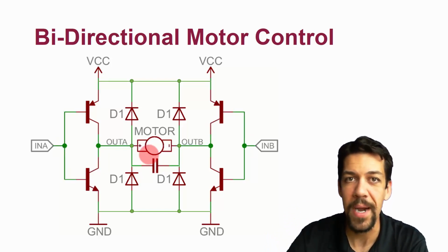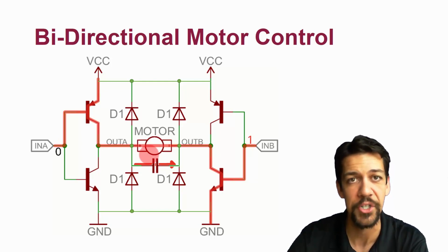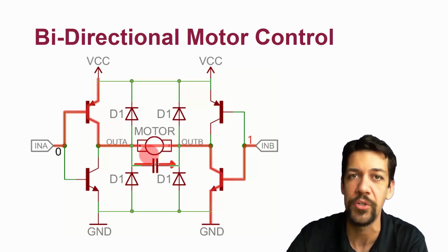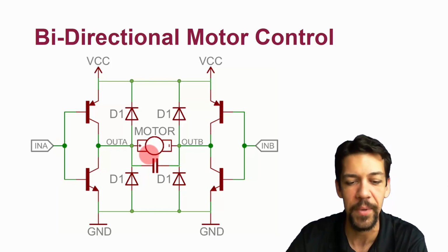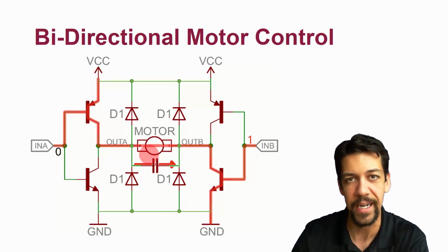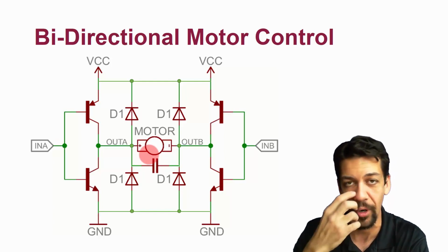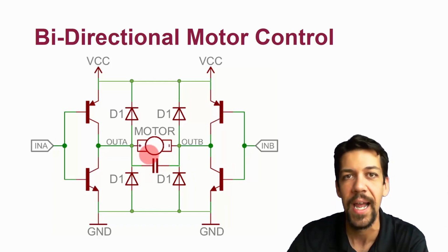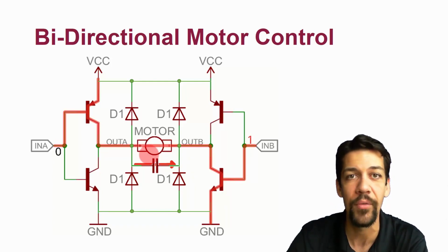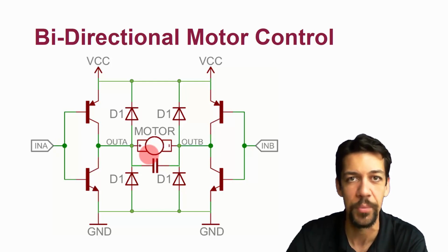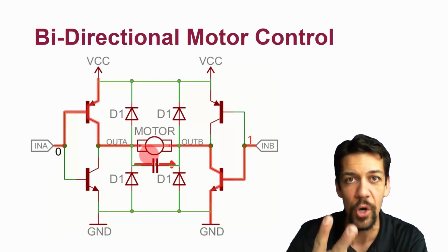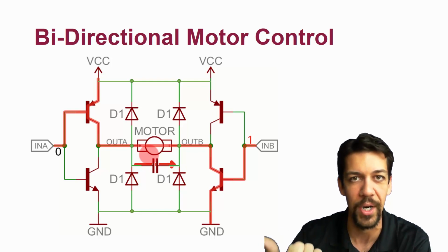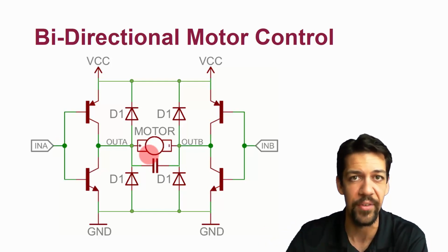Now, we've been looking at primarily control circuits for DC brushed motors, but for DC brushless motors, it's very similar, except we're controlling individual coils, and those coils need to be coordinated and driven bidirectionally or monodirectionally in the same way. So we would use arrays of these things. For example, one of our H-bridge chips, the quadruple H-bridge chips, could drive 2 coils in 2 directions. So that would be 2 motors, basically, because you can think of a general motor, one single brushed motor, as 1 coil that I can drive in 2 directions.